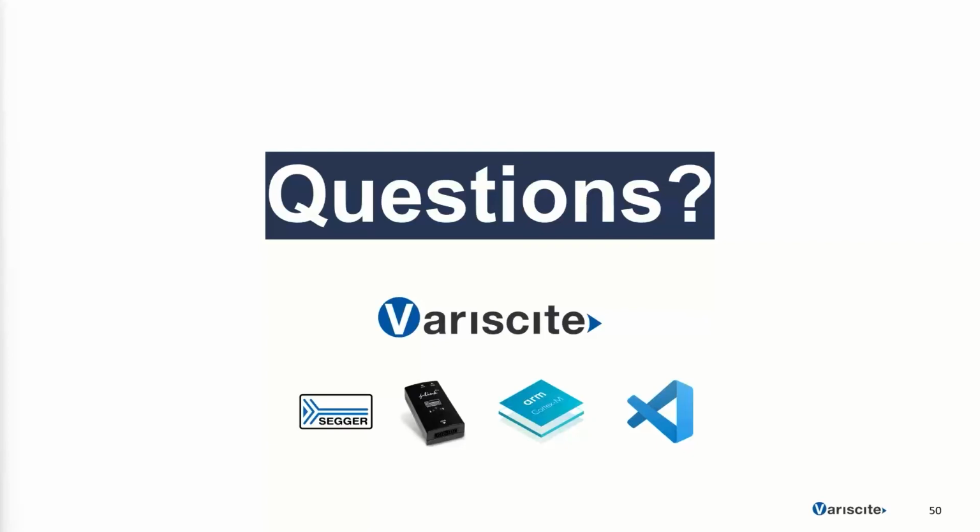And so if you follow this approach, on the Linux side, you can write an application that sends data through that serial port, and then you'll receive it on the M7 side, and you can also respond from the M7 and send it to the A53. So on the Linux side, it basically looks like a serial interface. On the M4 side, there's an API inside of the example that you can use to get started. So again, go to the examples directory, look at the multi-core examples. It's something like the string echo example or something like that.